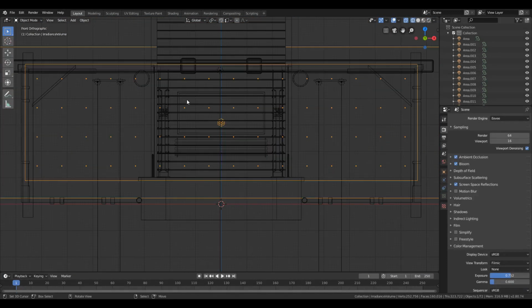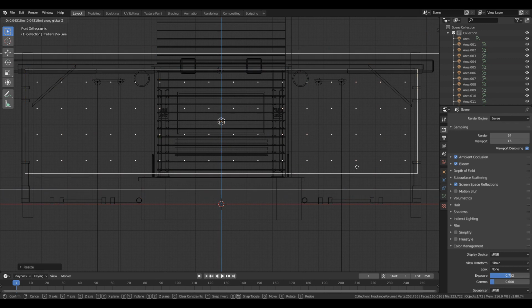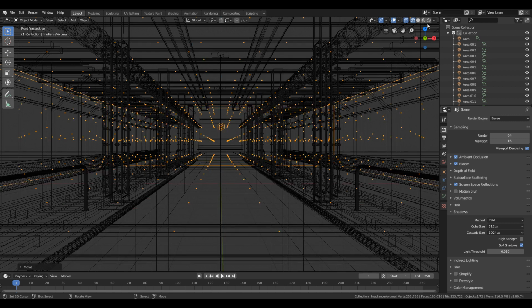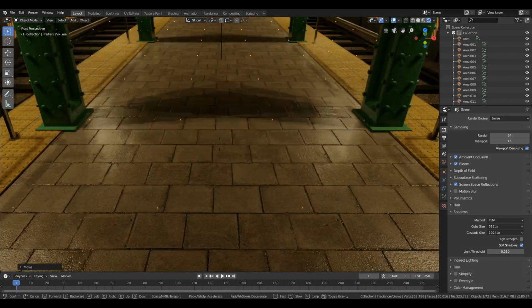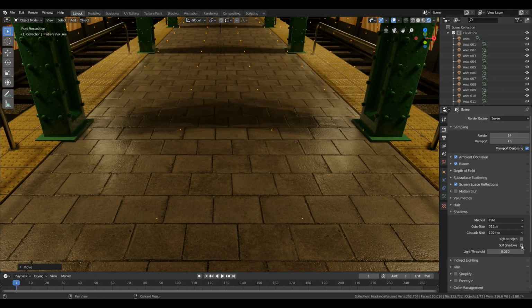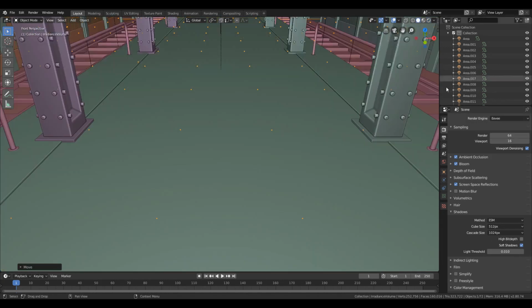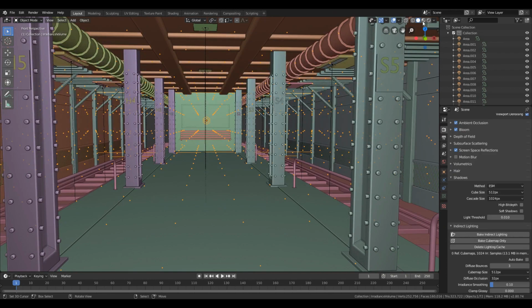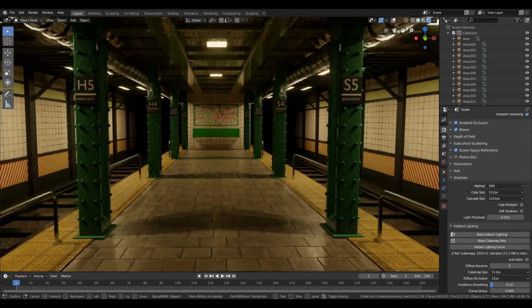Here's a simple trick. If you don't want to have bounce light on any of the walls, for instance, I want the roof to be darker, so what I did was I just moved the inner box of the irradiance slightly below the roof wall. And if you check the soft shadows in the shadow tab and bake again, it will give your shadows a soft feathered effect.